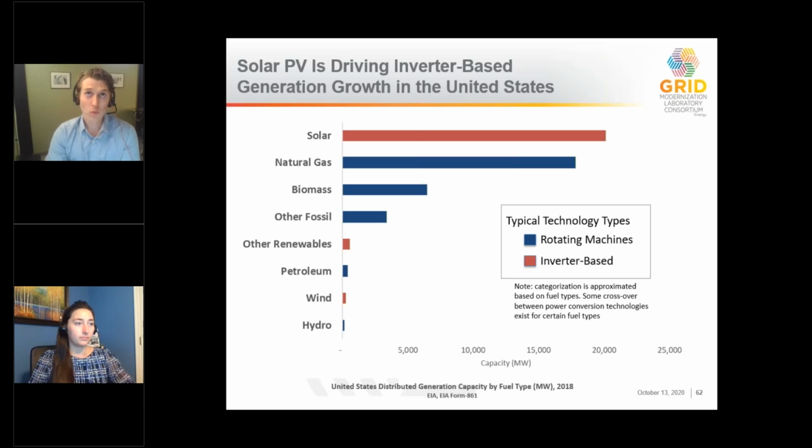So when I say inverters can't sustain island, it's caveating that they're grid interactive inverters that are certified to a specific certification, UL 1741, that tests specifically that they are not able to sustain an island, that they can detect and disconnect from the system.